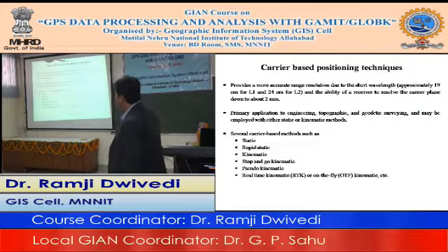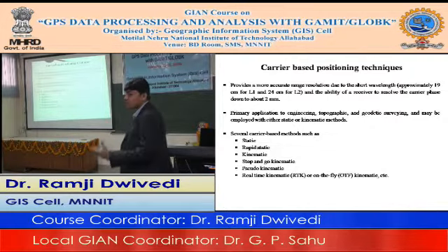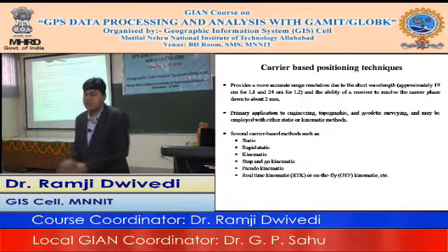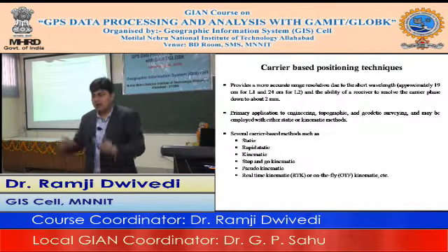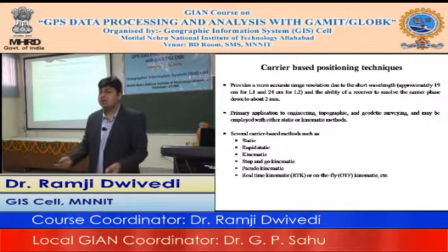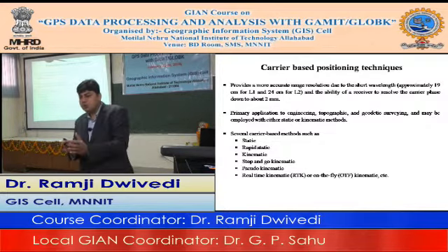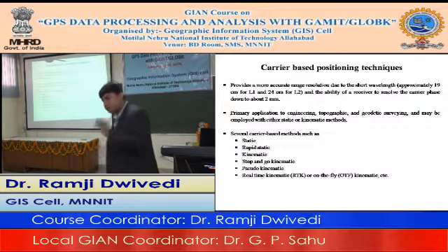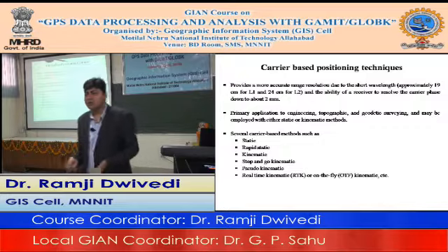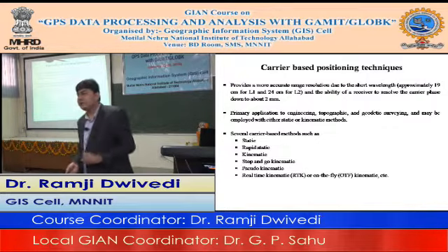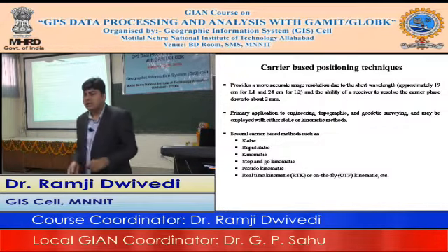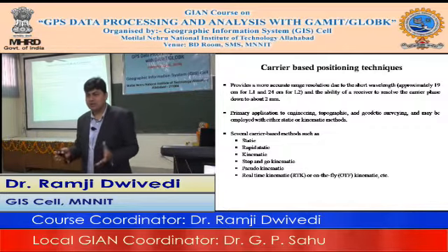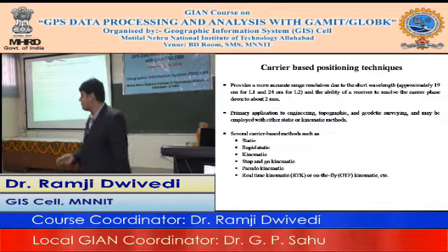So several carrier based methods have been developed so that you can move either in a static sense or in a kinematic sense, so that the accuracy in your estimate should improve whether you change from one mode to another mode. Obviously the static one is the most preferred, most accurate one, which we are doing for crustal deformation monitoring. The data set which we are processing in GAMIT, all these are static receivers. They collect 24 hour data throughout, and you use those RINEX files for processing.